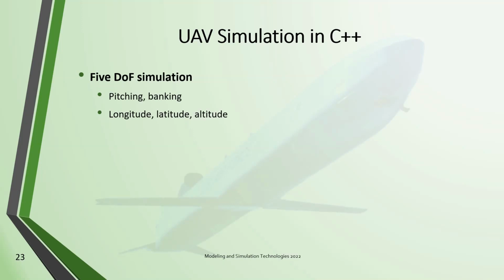So we have true longitude and latitude. The aerodynamics, as I said, are trimmed aerodynamics, represented by a flight polar. Now, there are no real surfaces that are modeled, but the drag of the trimmed surfaces is included in the drag of the flight polar.